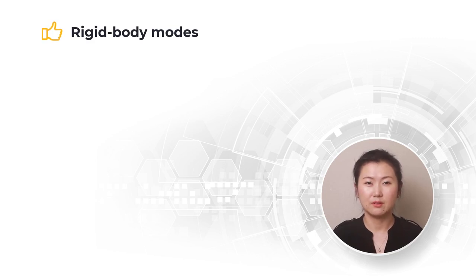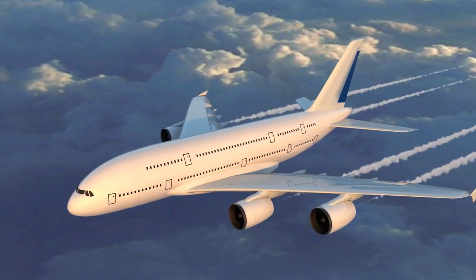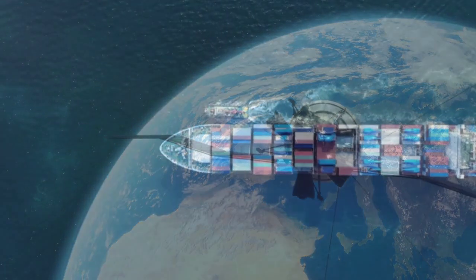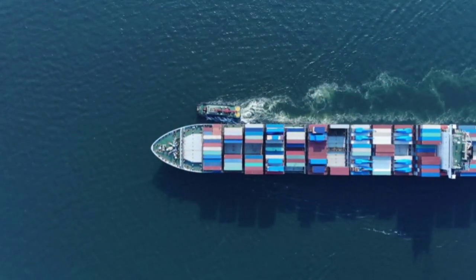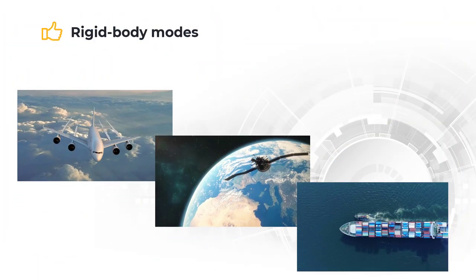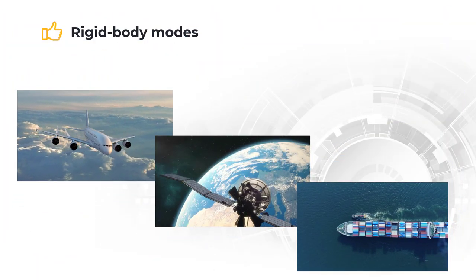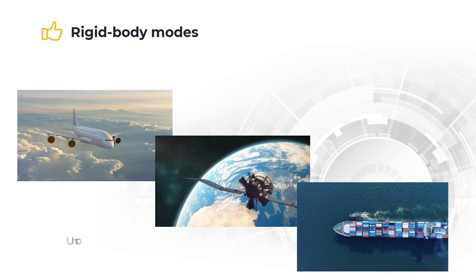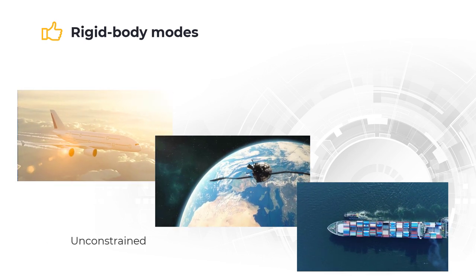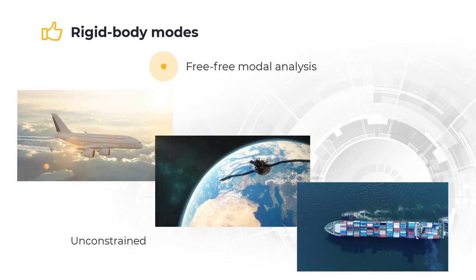Now, let's move on to the case when we do expect rigid body modes in our model solution. In engineering, there are some applications that do not require boundary conditions. For example, aircraft fly in the air, satellites orbit in space, boats drift in the ocean, to name a few examples. The goal of conducting modal analysis for such systems is to find out the dynamic characteristics of the system when they are unconstrained. We call such modal analysis free modal analysis.